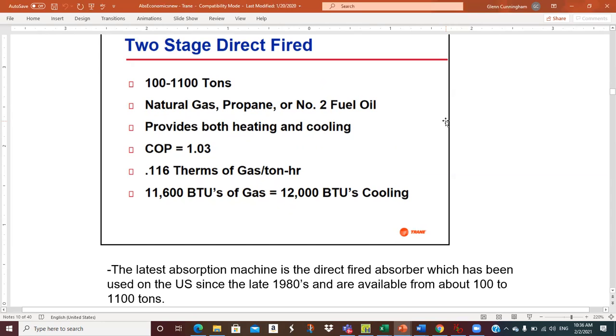So the higher the number, the bigger the pain it is to utilize, the more viscous it becomes, and the cheaper it becomes. Number 6, you can buy low sulfur or high sulfur. And of course, high sulfur is cheaper than low sulfur because you probably have to do something to remove the sulfur dioxide, the sulfur compounds, from your exhaust gases when you burn it.